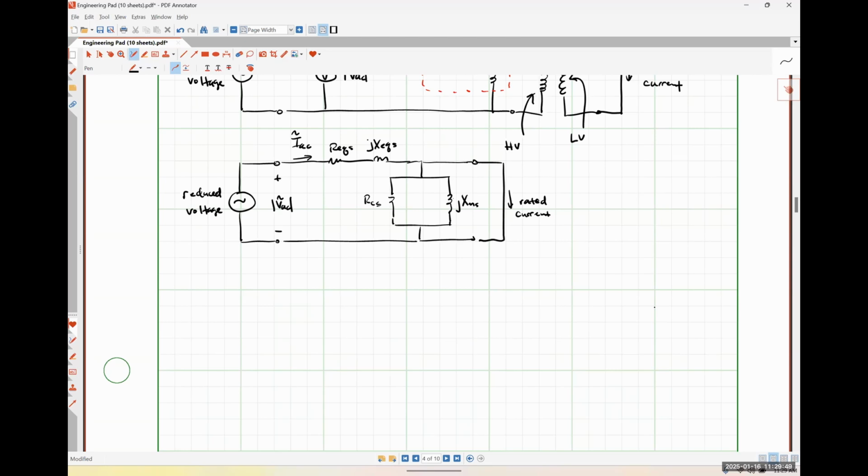If we didn't make that assumption, we could still do the circuit analysis, and technically speaking, it would be much more accurate. I say much more accurate. We're only going to be introducing around 1% error anyway, but the amount of analysis and math needed to do it would be much more difficult, because we would effectively have a situation where we would need to be applying mesh analysis or nodal analysis to an AC system, as opposed to simple things like voltage division and Ohm's law.